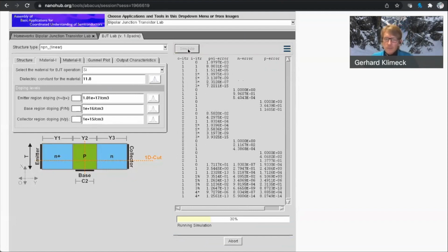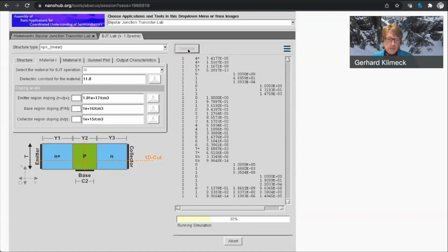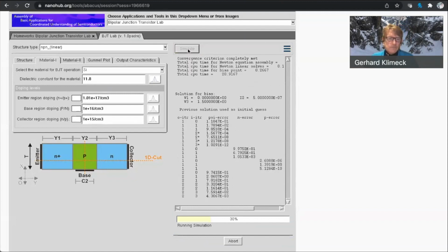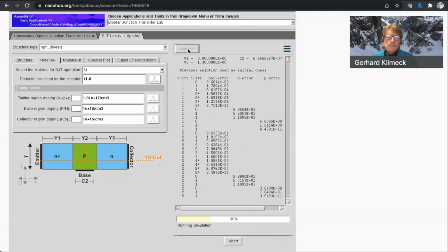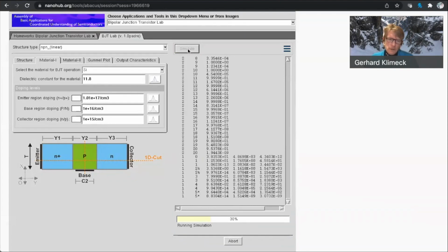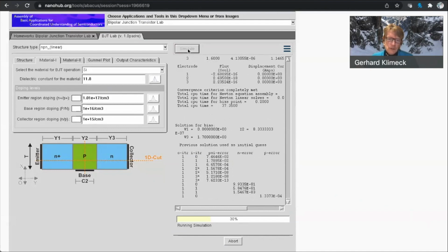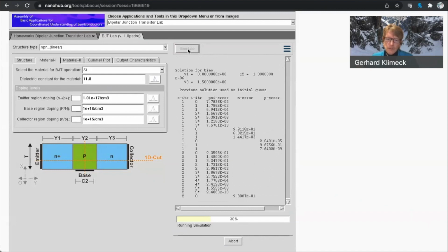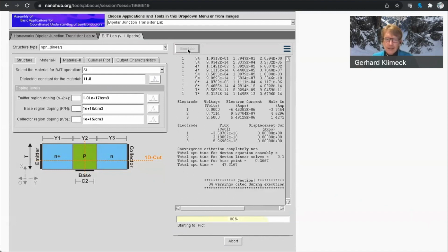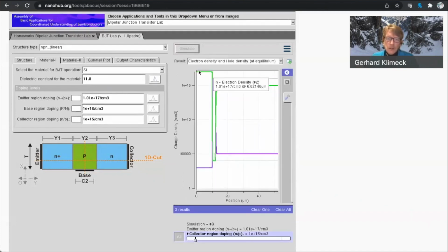It's not a run that has been done before. So this is really treading on different simulations. So this is not canned. And in a minute or so, we should have the runs be ready. By the way, this is solving the full drift diffusion equation in this PADRE tool. So here you now see a more typical staggered doping profile of 17, 16, 15.